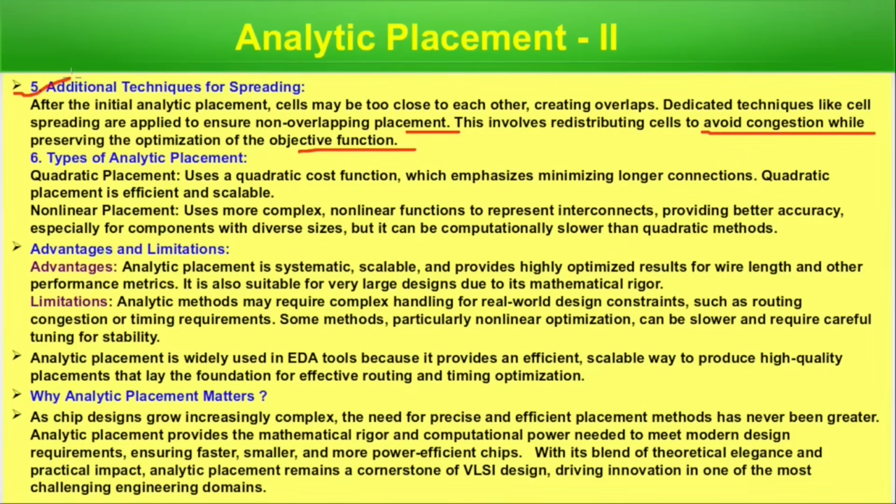The main objective is to position the cells in such a way that in routing, the length could be less. If length is less, it means power loss is less, heat generation is less, timing delay is less. So positioning is the key, and then how to optimize their position so that there is no congestion, and routability is easier. This situation is so critical because the number of components is huge and the connections between them are complex, because the functionality is complex. Day by day, the number of devices is increasing and a chip is performing more and more complex work. So connections are complex.